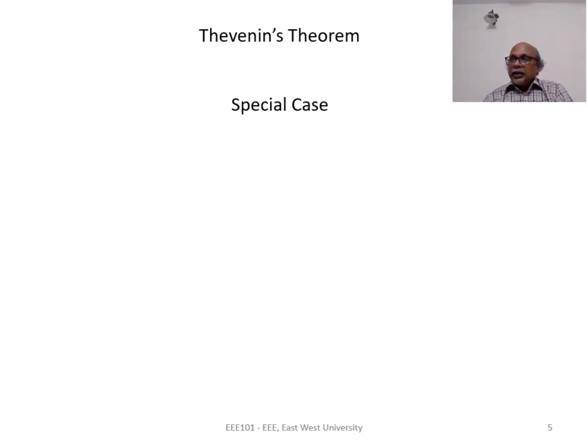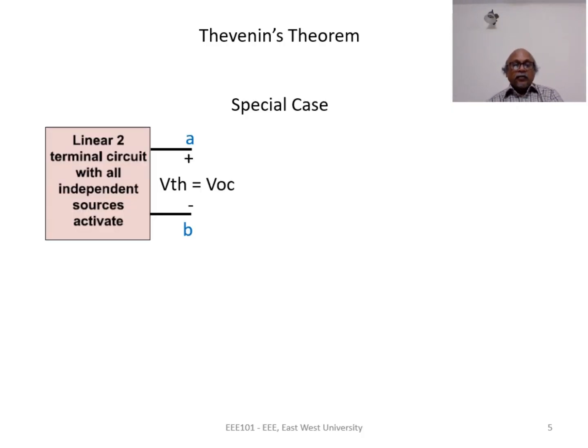We measure or calculate two data sets. First, we disconnect the load between node A and node B, and under open circuit condition, we find the voltage VOC.